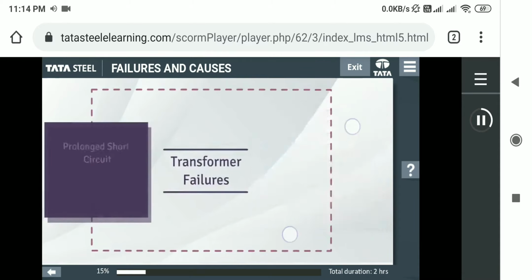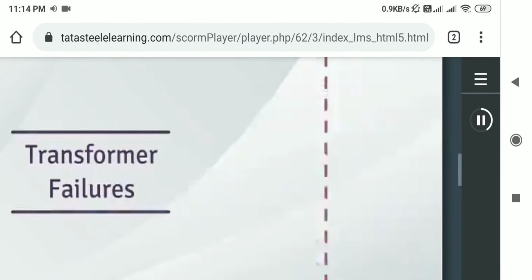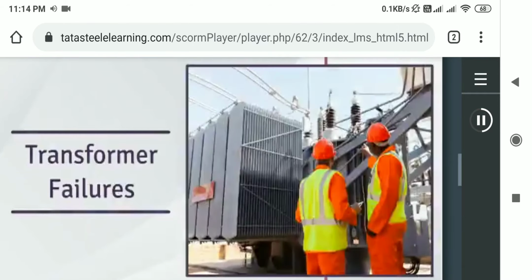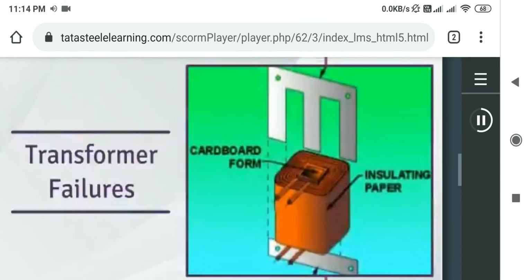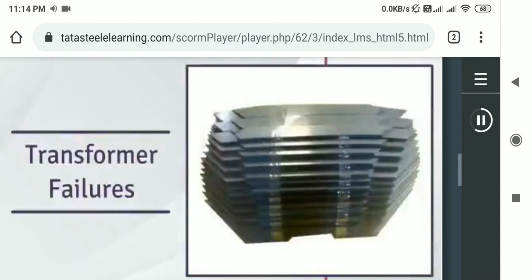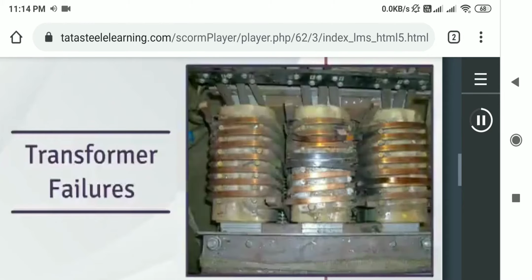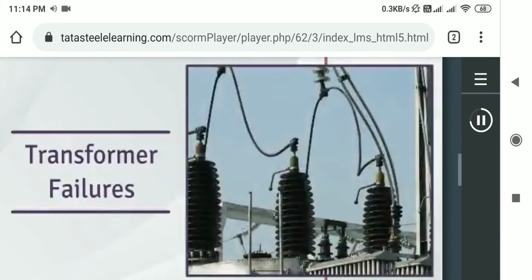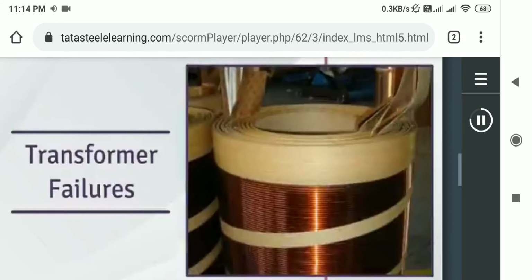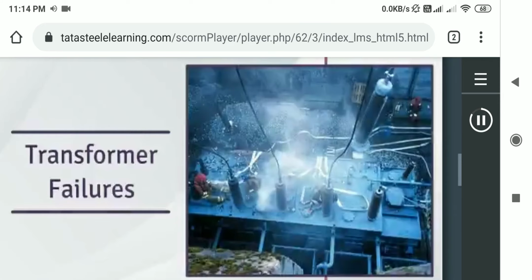Power theft, prolonged short circuit, faulty operation of tap changer switch, lack of installation checks, faulty design, poor workmanship, improper formation of core, improper core bolt insulation, burr to the lamination blades, improper bracing of joints, burr or sharp edges to the winding conductor, incomplete drying, bad insulation covering, insufficient cooling ducts in the winding, bad quality of raw material, transit damaged transformers.